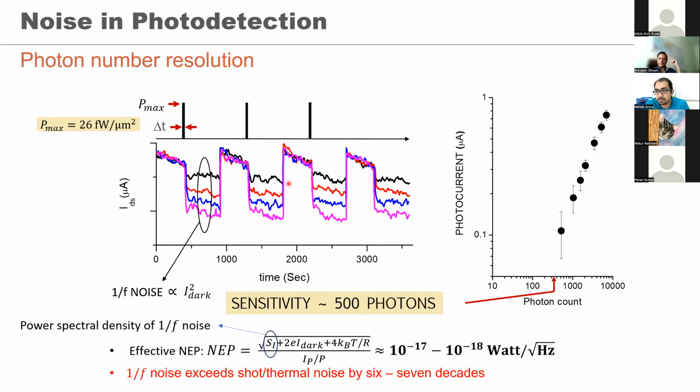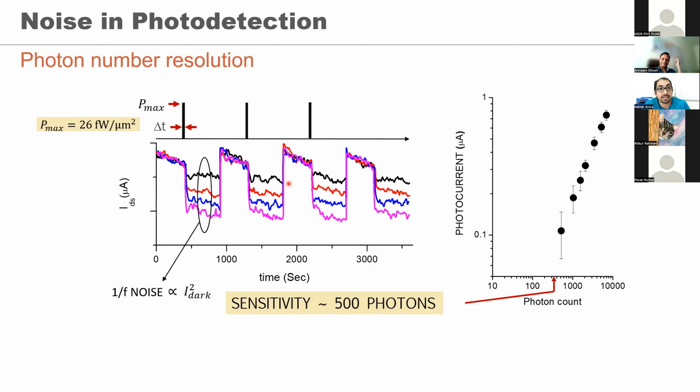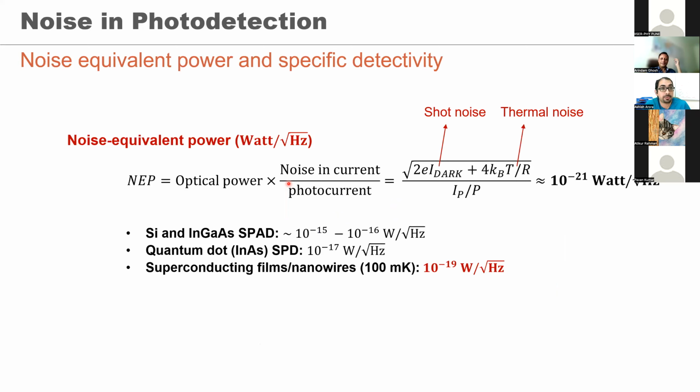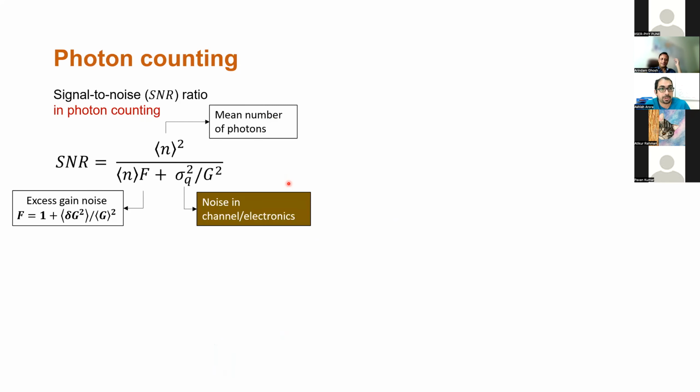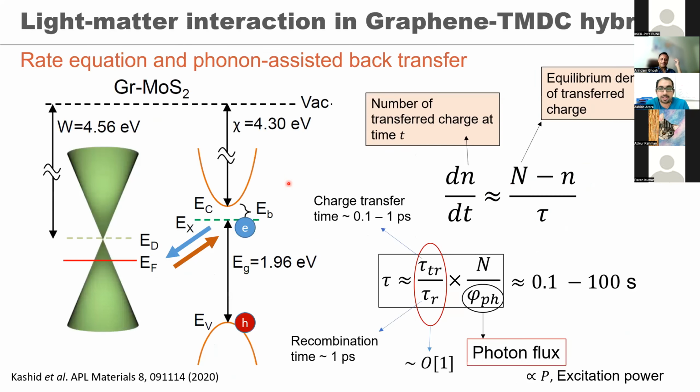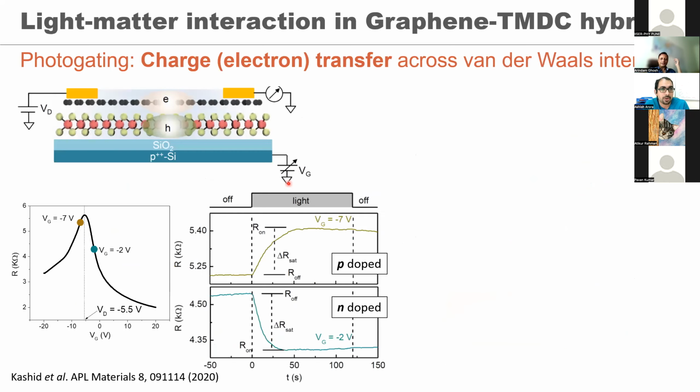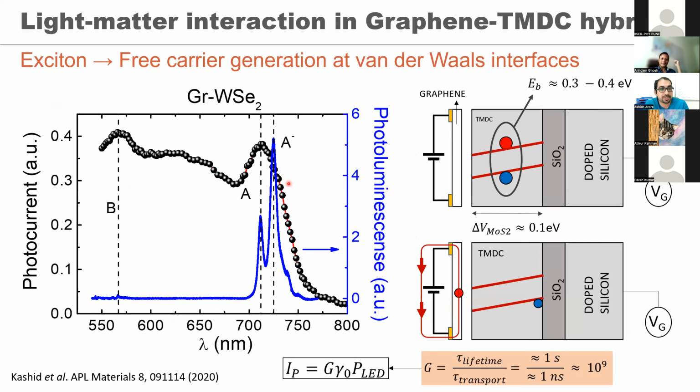I see. So this is what I was wondering, because these excitons normally are known to have very large binding energies. That would mean the radiative recombination times would be very, very short, of the order of hundreds of femtoseconds. Correct. So wouldn't that affect the photoresponsivity in a negative way? Because this will take out all the responsivity within the MoS2 layer and would not let it go to the graphene.